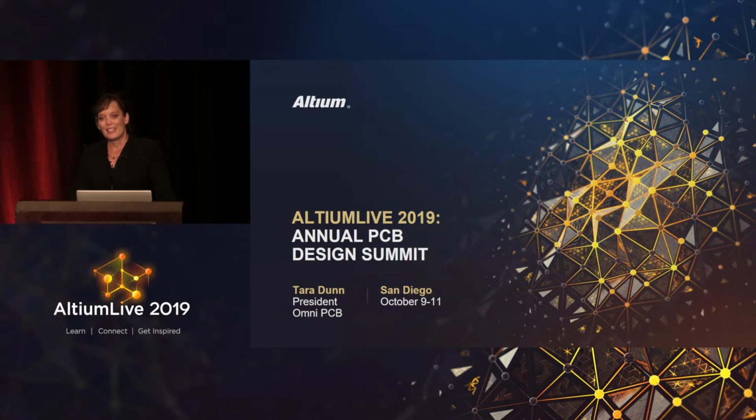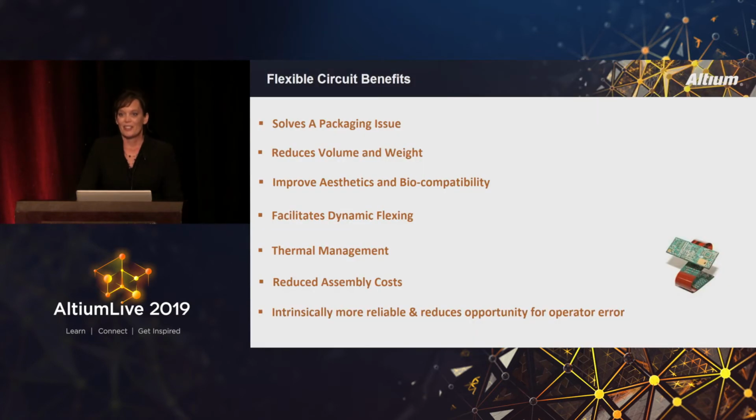But the other thing that really stands out is that was really a good lesson in the progression of all the different things you can do to make a circuit more flexible when you're worried about the bending and folding, right? We crosshatched the shield, grain direction, added polyimide stiffeners. So many different tips and tricks that you can use when you're working with the flex circuit.